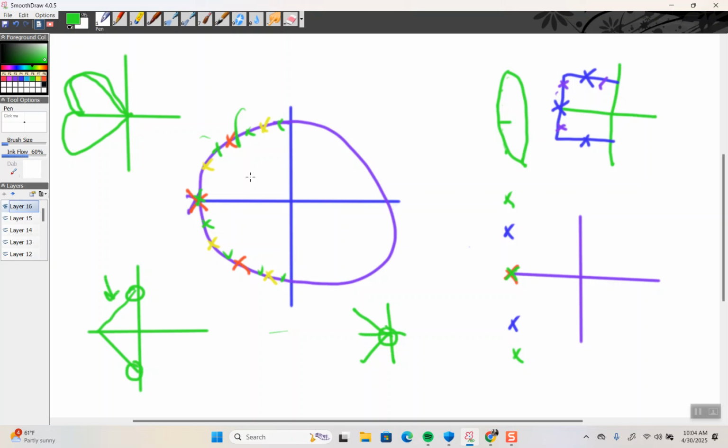But yeah, do it from scratch if you're trying to really understand it. But you can use those constant generators just fine. You've seen three circuit architectures: RLC, multiple feedback, Sallen-Key, right? To make low pass filters. And now you can adjust the constants, and high and low pass are fine too.